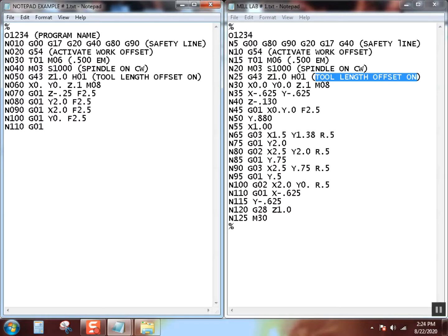And finally, to finish up, this is pretty simple. Like I said, we just milled a simple square. I'm going to go back to X0 at 2.5 inches per minute. Once again, I do not have to type these F's or these G01s, but when you're first starting out, it just keeps things clearer. Another time for Control S. Save that. Get used to saving it because your computer will lock up any minute, and what you don't save, you will lose. I've already had my computer lock up 3 times today. This turned out to be a great day.